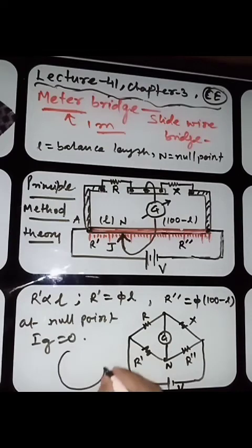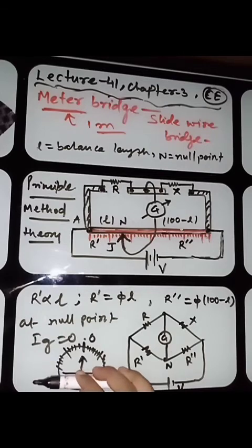Remember, this is the galvanometer. Look here. In a galvanometer the readings are given in this way. This is 0, then 1 2 3 4, 1 2 3 4, in this way, and this is the pointer. Right now this pointer is at 0. This pointer moves when current flows to this side, and it moves to the other side when current flows to that side. Remember, this pointer doesn't start from here. The pointer remains at 0 if the current is 0.